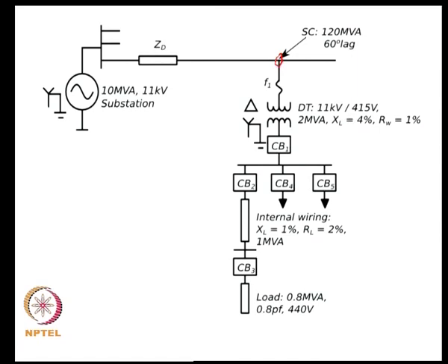So, if you take a home, it would be at 230 volts or 415 volts after the meter, okay, because the meter is actually owned by the utility. You do not go and make any changes to the meter. Your responsibility is whatever is downstream of the meter. So, depending on the size of the facility, for large ones you might put your meter all the way up at 11 kV. For smaller homes, it would be at the consumption level. Okay. And here you say you want to add a fairly large facility,